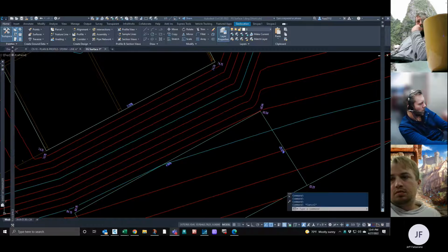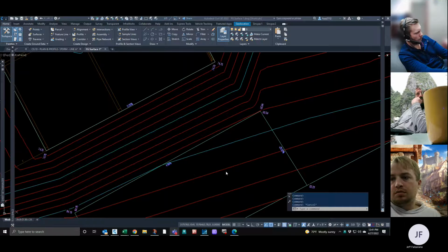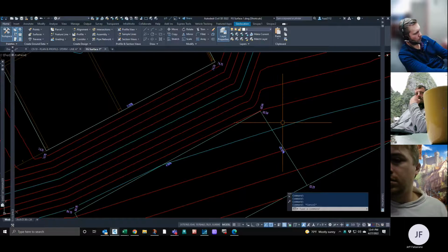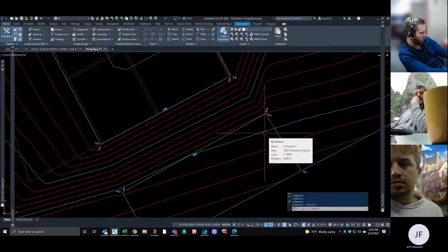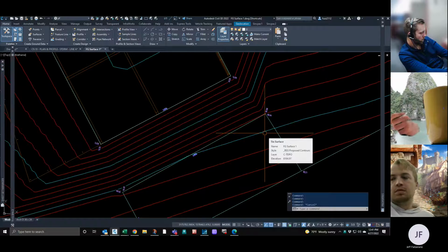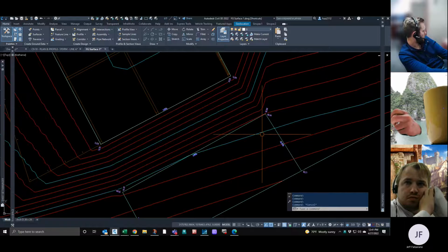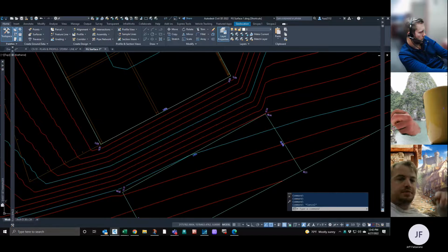Okay. Is there a way to quantify the foot thick with the feature lines, or do I just start the top of wall a foot away from what we just drew? Yeah, I would draw your wall in where you think it's gonna be in your P base, and then have it just a foot thick, and then just draw your bottom feature line to that side, the bottom, and then draw your other feature line coming off of your building on that side.